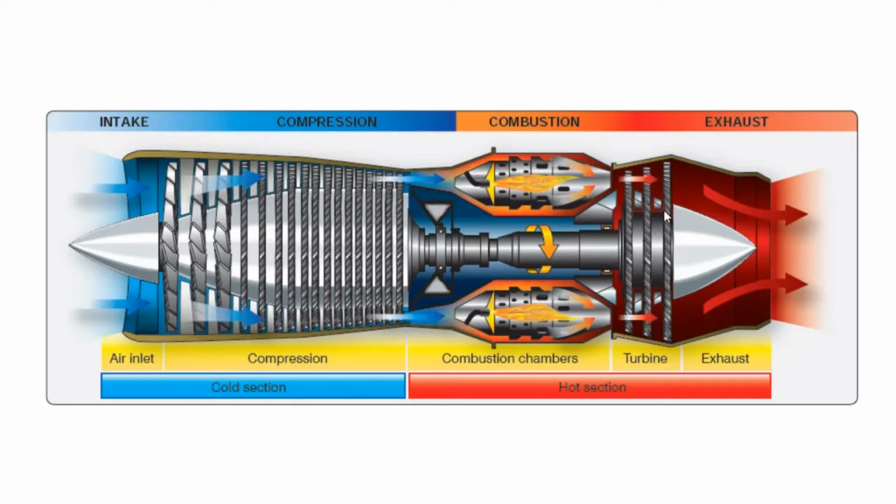The part of the energy is consumed by the turbine section and the other part is transferred to the exhaust, which produces the thrust to drive the aircraft. This distribution of power depends upon the application of the engine. In helicopters, the energy which is diverted to thrust is very little compared to the energy which is utilized in the turbine.